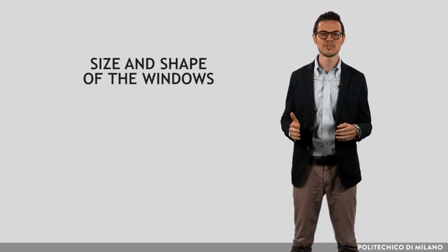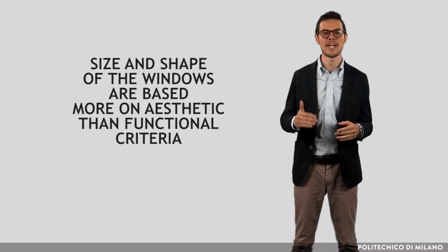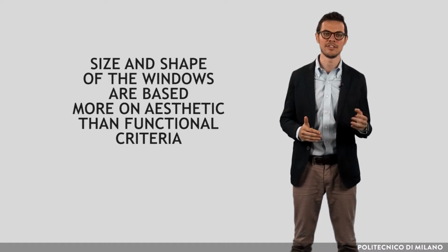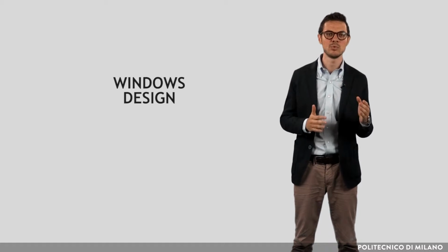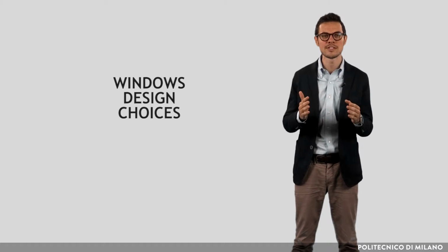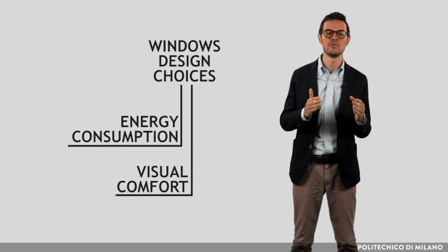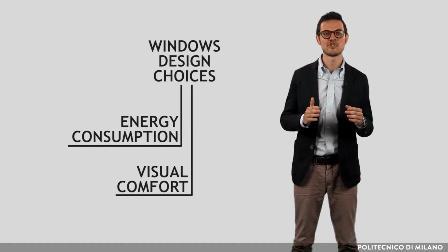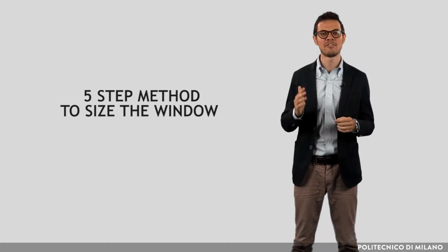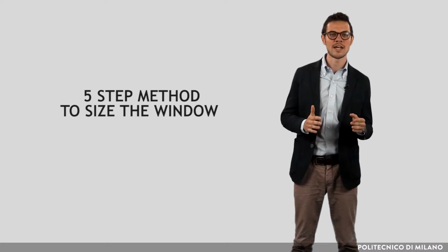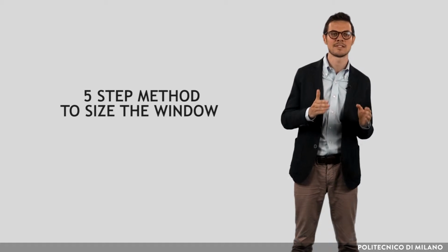In current design practice, the size and shape of the windows are generally based more on aesthetic than functional criteria, despite the fact that window design involves choices that have a great impact on energy consumption and on visual comfort. For such a reason, we will introduce a 5-step method to size the windows at the earliest stages of